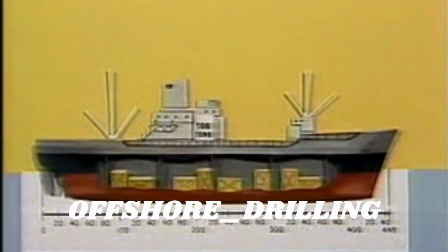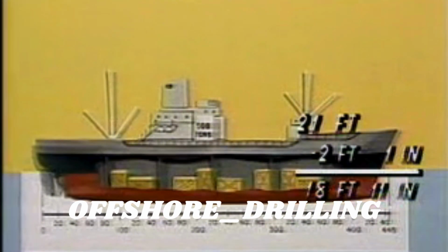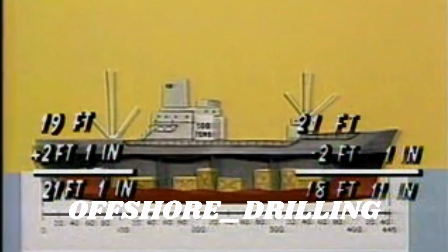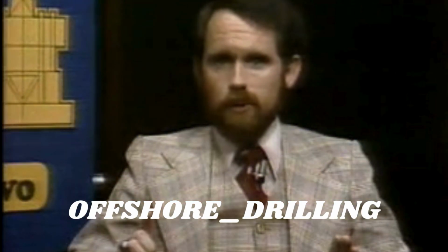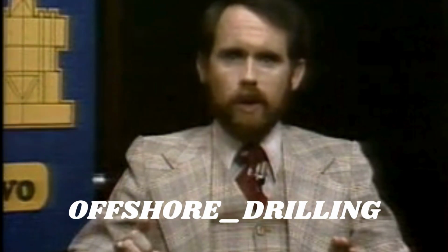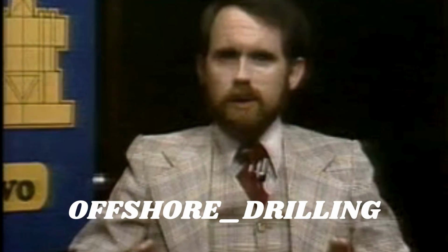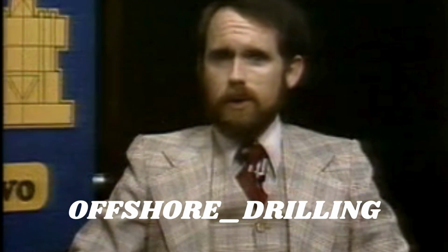Applying these amounts to the original draft, we get a final forward draft of 21 feet minus 2 feet 1 inch, or 18 feet 11 inches, and a final draft aft of 19 feet plus 2 feet 1 inch, or 21 feet 1 inch. Notice that the draft did not change because we didn't add or discharge weight. Now let's consider a case where we do change the draft by increasing or decreasing weight.